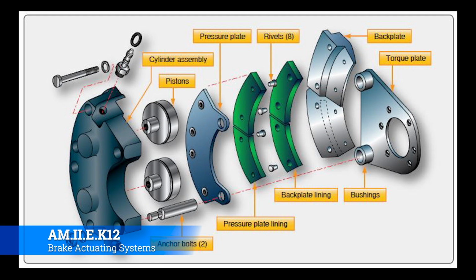You simply torque two different bolts that are typically safetied, take those bolts out, and the brake caliper will slide up and off of the rotor. Then you can do whatever maintenance you need to those brake pads or the pistons, and then you just do it all in reverse. All that's left is to bleed the brakes, which we'll show you how to do here at the hangar.